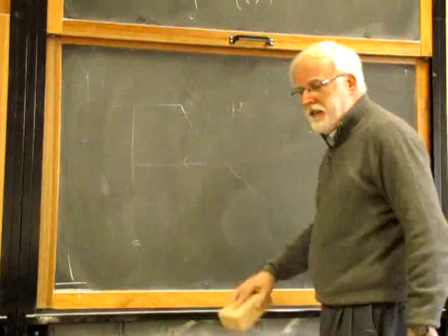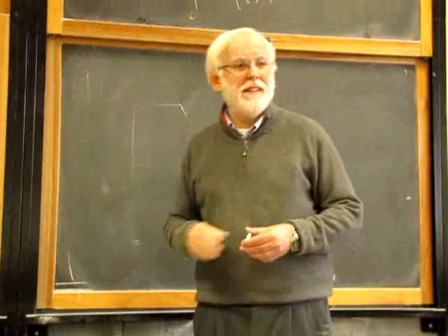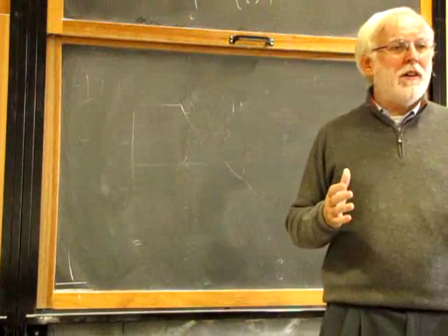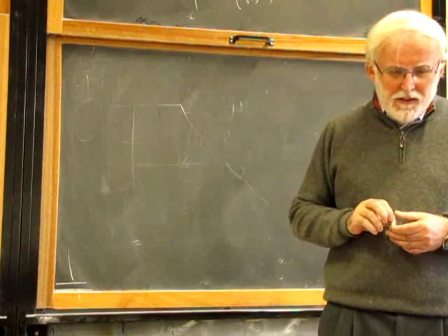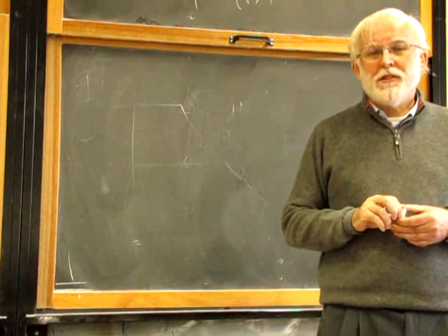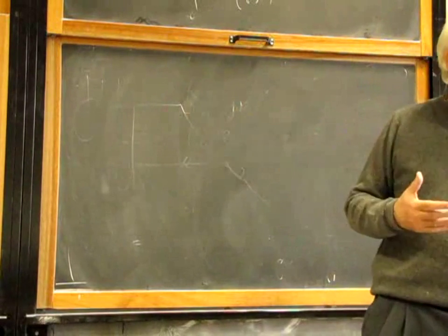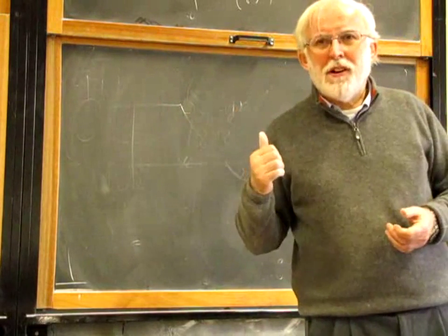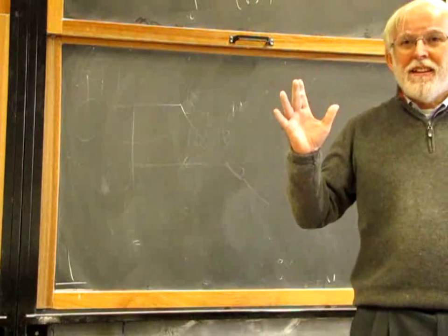Okay, on Friday we will start with the switch averages, because this system to solve the circuit worked. We found a solution. You can apply it to any converter, and I once had a student making his thesis with me, and we had to analyze a different topology that was not found in literature to find the transfer function. He applied this method and he got the result, no problem. But it's a heavy method. It's very complicated. Why? Because we are averaging all the circuit completely.